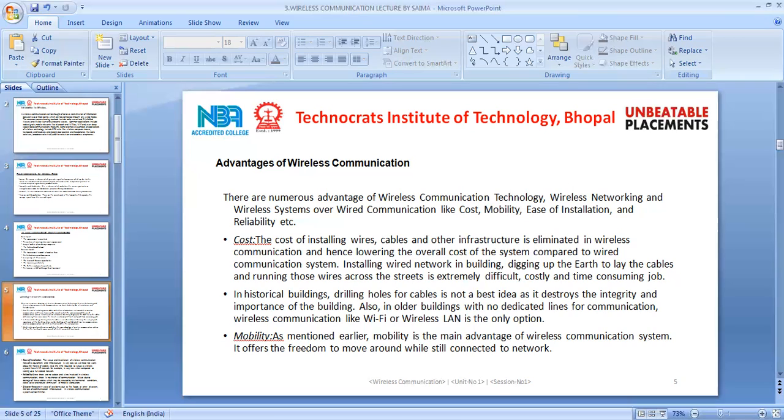And the next technical challenge is user mobility. Mobility is an inherent feature of most wireless systems and has its own importance. Fading has already been discussed above. A second important effect particular to mobile users in a cellular system is that the system has to know at any time which cell a user is in. If there is an incoming call for a certain user, the network has to know in which cell the user is located. If an MS, mobile station, moves across a cell boundary, a different base station becomes the serving base station. In other words, the mobile station is handed over from one base station to another.